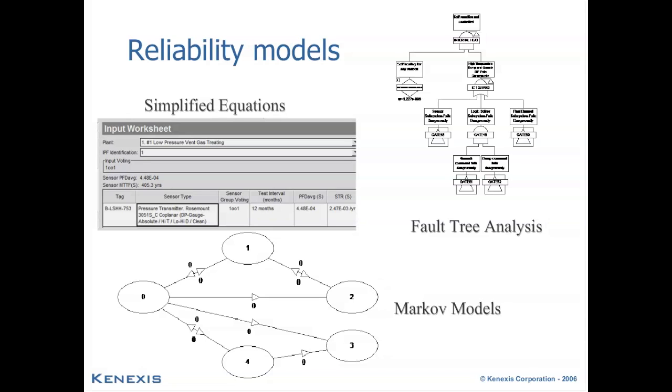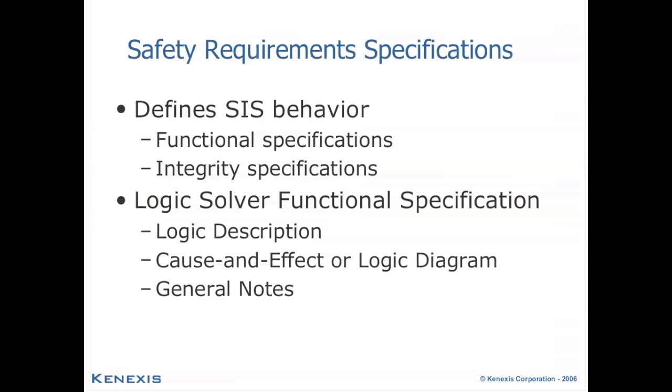Those reliability models that are permitted within the standard include simplified equations, fault tree analysis, and Markov models, which have individual strengths and limitations, but all are considered suitable for determining the suitability of a particular design to be used in a SIL application. And that would be the SIL verification step.